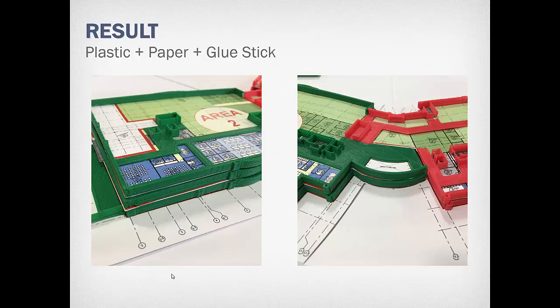and also to get the two different sides to merge up, we decided, one, to use a different color plastic on either side, but two, we had to be very careful about those points where the two halves of the model would join together. There is just a little bit of expansion that can happen when you're printing with a conventional plastic like ABS. So we were very careful to scale those back just at the interface so that they would ultimately meet up and sit together pretty well.